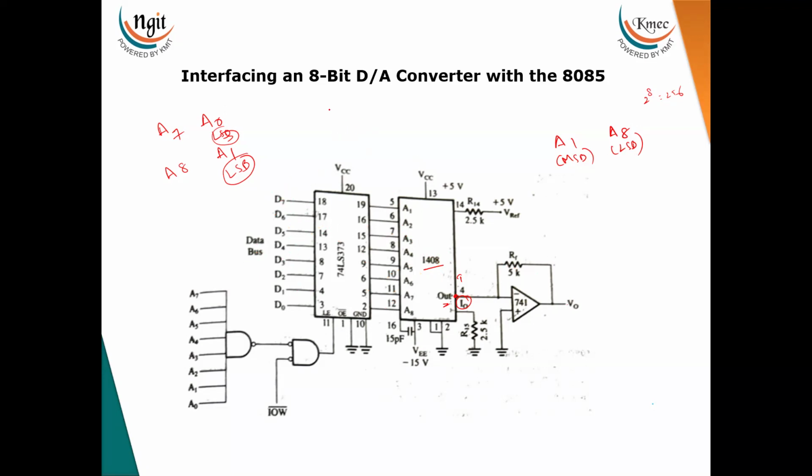So now for this, what is the instruction? OUT, so here the processor is writing the data. And what is the port address for this one? All address bits are connected directly to the NAND gate. Here the decoder is what? A NAND gate decoder is used.